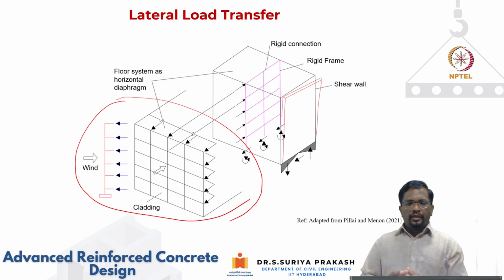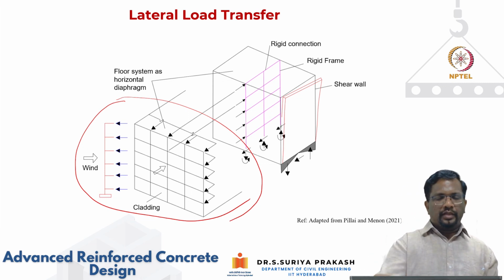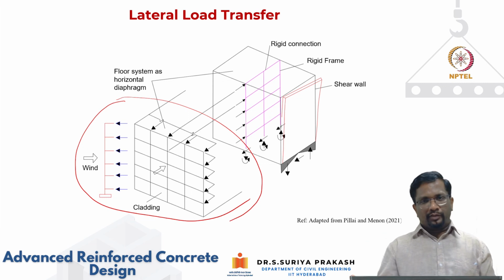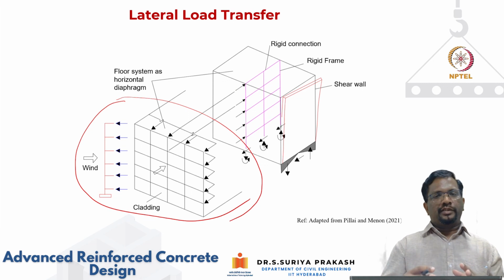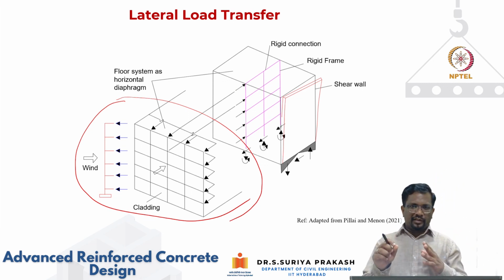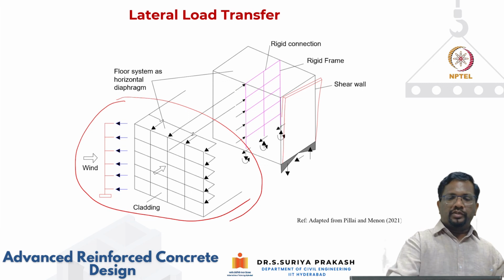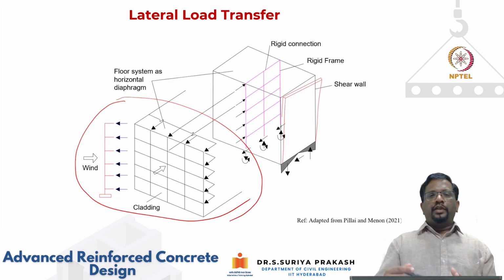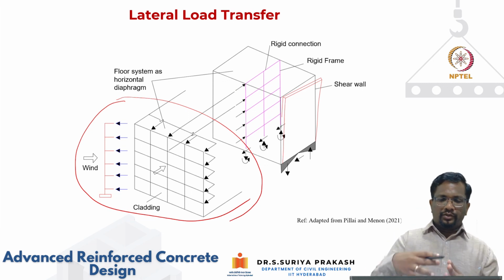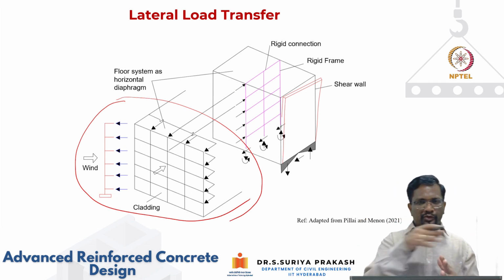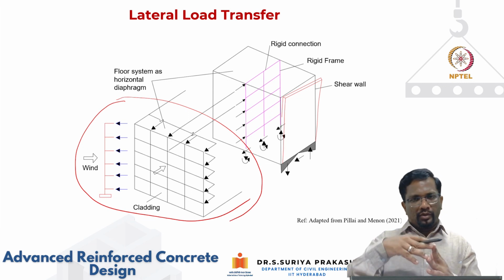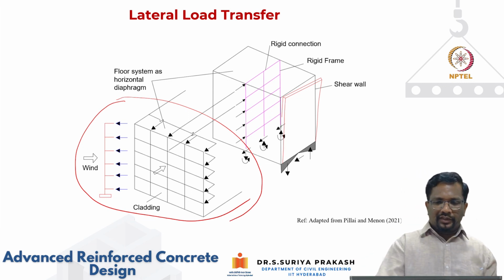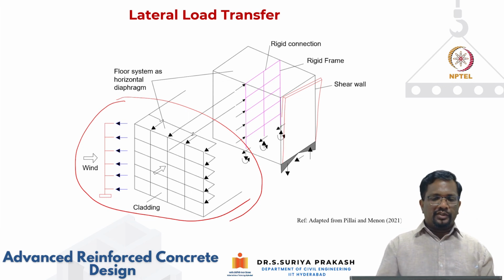Usually, whether you are doing reinforced concrete cast in place construction or precast, we make sure that we develop rigid connections, unless it is explicitly designed as a shear connection, in which case you transfer only shear. Most of the time in cast in place construction they are all rigid connections, right? The columns and beams are poured together with reinforcement continuity, so both the columns and beam rotate by the same magnitude. So you have a rigid connection, and we call that a rigid moment resisting frame if it is designed properly.